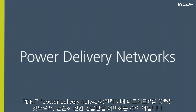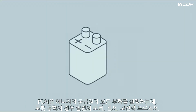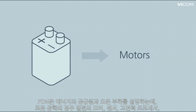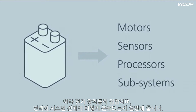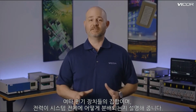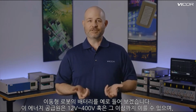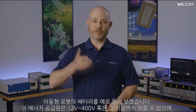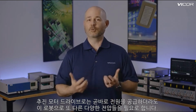Before we dive into the examples, I'd like to explain the concept of the power delivery network. So a power delivery network, or PDN for short, is more than just the power supply. It describes both the source of energy and all the loads, which in the case of robotics is a collection of motors, sensors, high-power processors, and other electrical subsystems, but also the strategy and implementation of how the power is distributed throughout the system. Take, for example, mobile robot batteries, which are an energy source ranging from nominally 12 volts all the way up to 400 or higher, typically routed to directly power the propulsion motor drives.